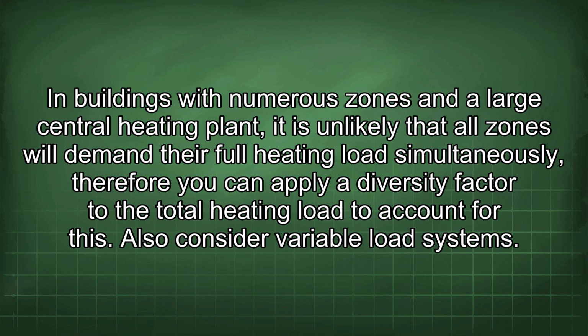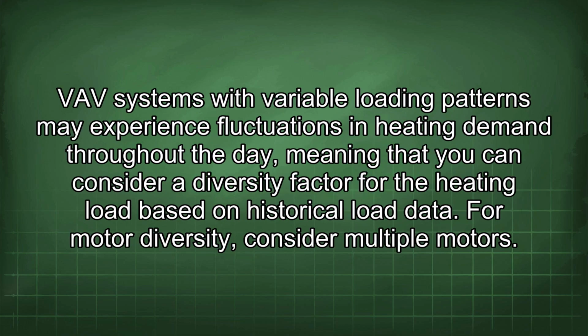Also consider variable load systems. VAV systems with variable loading patterns may experience fluctuations in heating demand throughout the day, meaning that you can consider a diversity factor for the heating load based on historical load data.